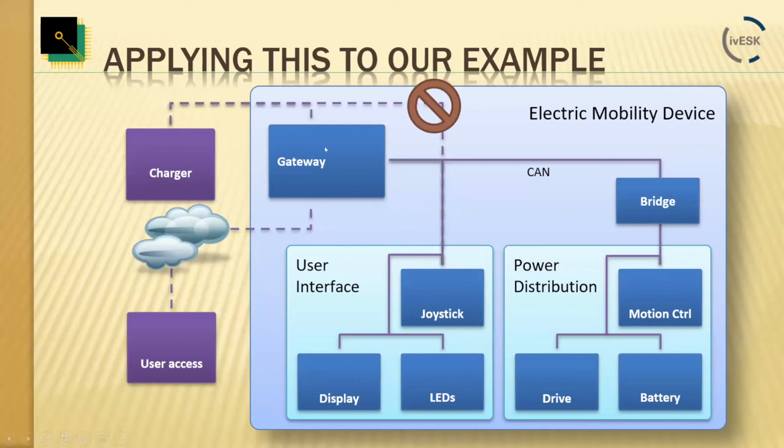Of course some manufacturers might have ways around it and specific operating modes where more data gets through, but in general the idea is, whatever you connect to the CAN networks, try to avoid a direct connection and put something in between: a gateway, a bridge, whatever.